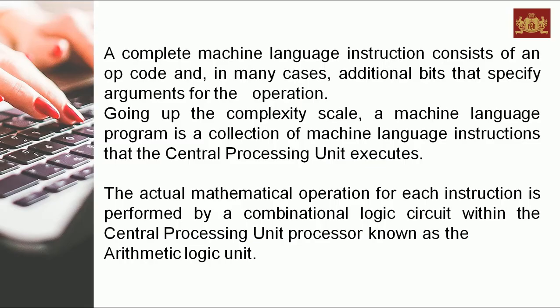A complete machine language instruction consists of an opcode and, in many cases, additional bits that specify arguments for the operation. Going up the complexity scale, a machine language program is a collection of machine language instructions that the central processing unit executes. The actual mathematical operation for each instruction is performed by a combinational logic circuit within the central processing unit processor known as the arithmetic logic unit.